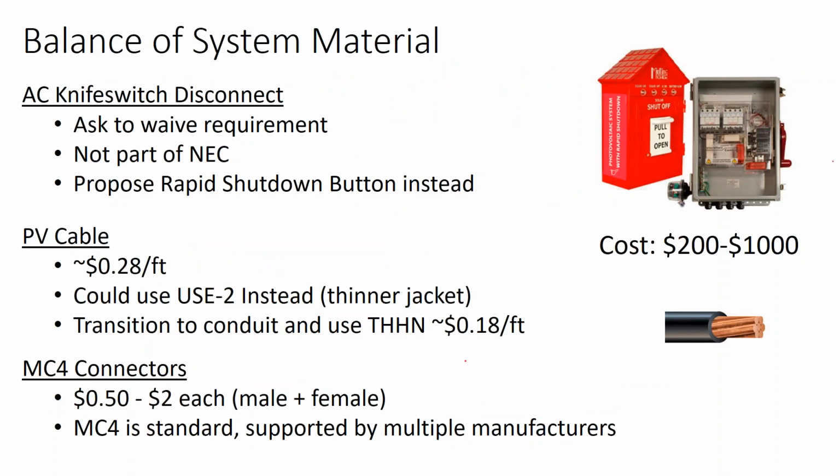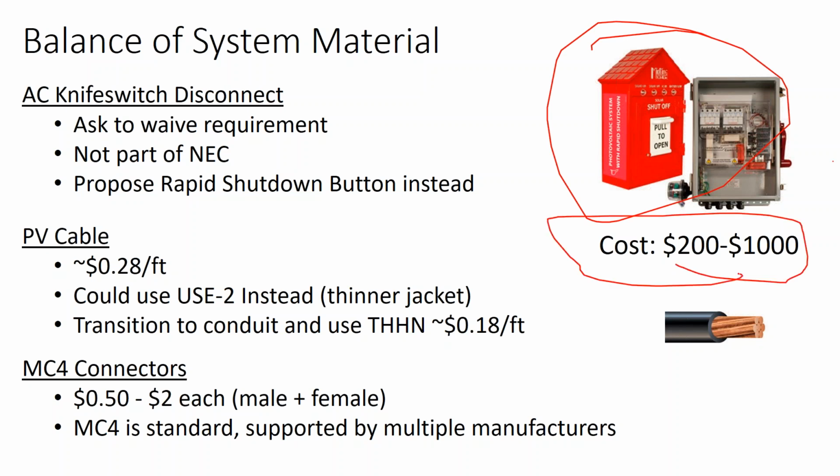So I don't use the system level disconnect buttons to tie everything together, mainly because they're so infrequently used on the market that they're still pretty expensive. So I don't think that it's worth buying them now, but it is worth it to just keep a space for a system level disconnect. And when you're doing your battery systems, you want to indicate in your signage outside the building that there is an emergency backup system in place, showing the fire department where to go in order to turn off that system level disconnect.